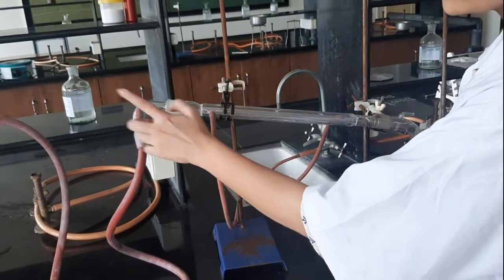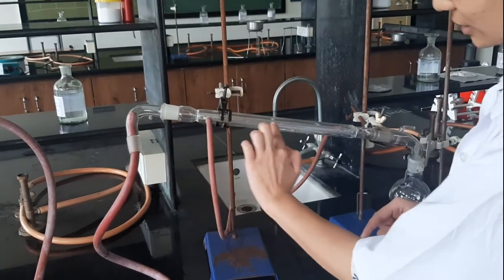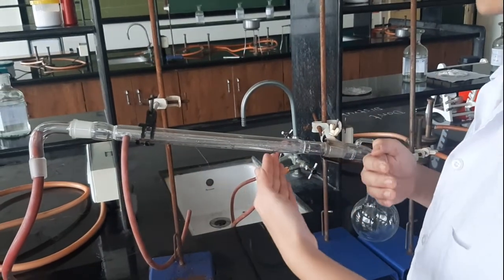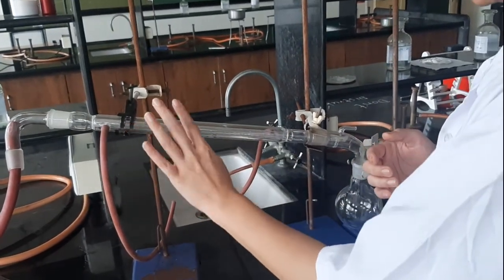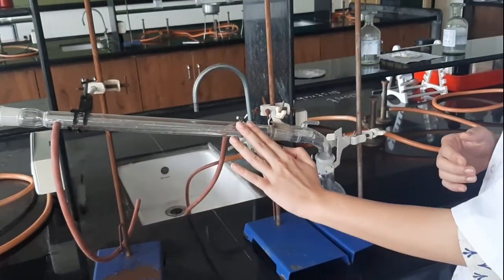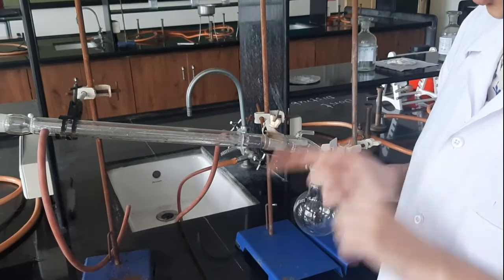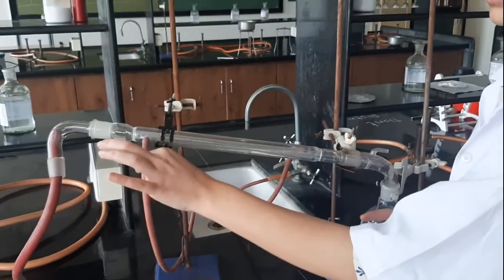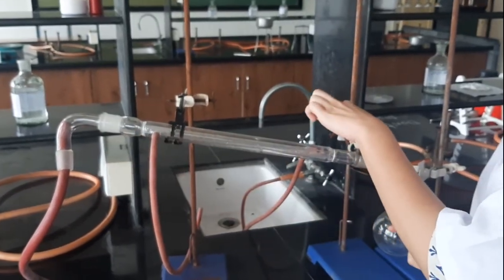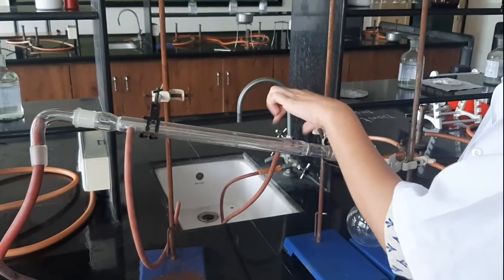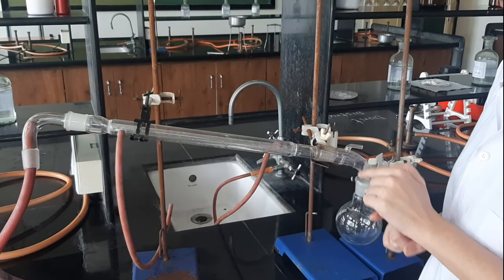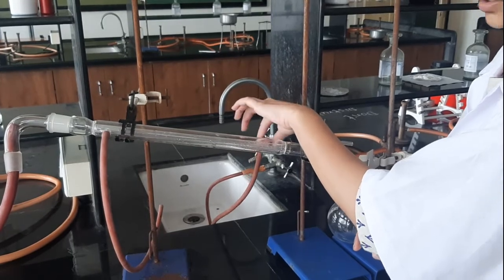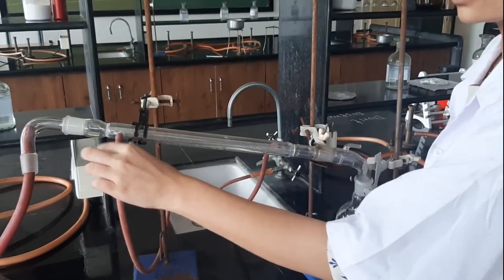From the steam which is generated there, it will move through the inner tube, and the cold fluid which we are going to use for cooling will be circulated through the outer tube. With this condenser, we are going to perform two processes today. One is parallel flow and the second is counter current flow. Parallel flow will be when we connect this tube to the inlet of the cold water, and the outlet will flow away. That is parallel flow. In the next process, which is counter current flow, we are going to connect this inlet with the tube to the tap, and from this outlet the cold water will be released.